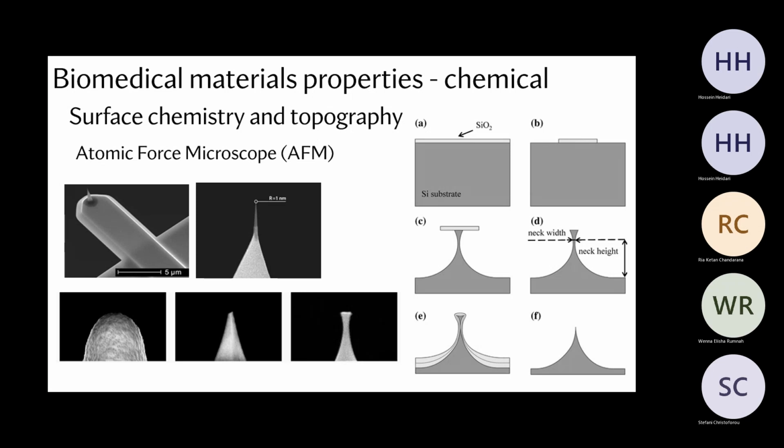So although this is maybe 10 nanometers, 20 nanometers, because the etchant is a diffusion process, if you give it enough time, it digs under, it actually eats into it further and further. And at the end, if you use the etchant that's suitable for SiO2, the first etchant that we used, and remove that covering layer, you're going to be left with this tiny protrusion with a very thin neck.